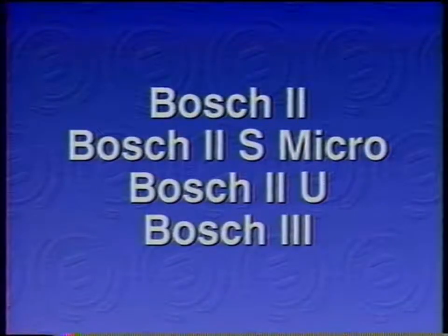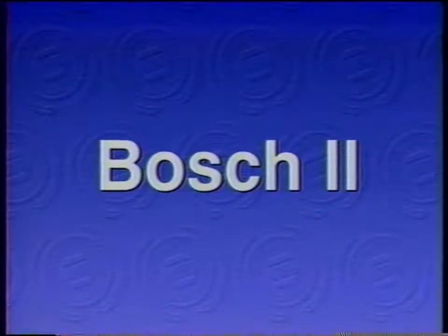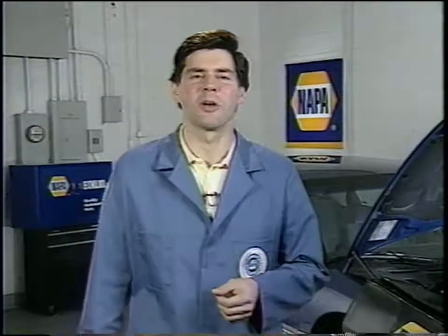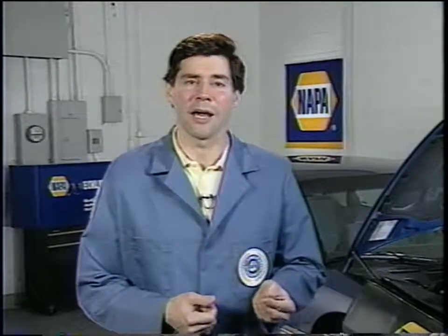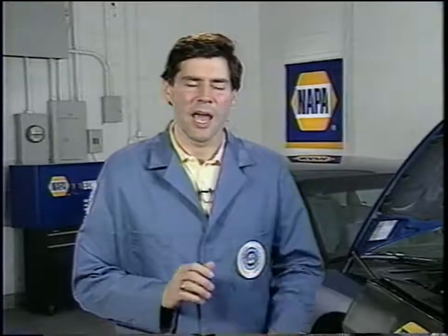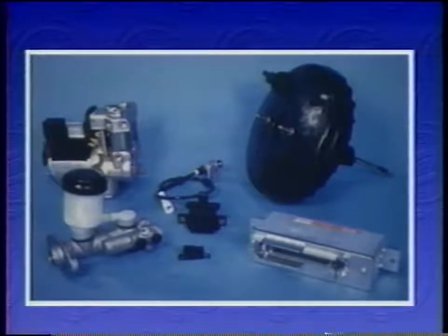Of the 4 Bosch ABS configurations, the Bosch 2 has the widest range of applications. And since it's been around the longest, beginning in 1981 on the Mercedes and on the Corvette in 1986, it's also the one you're most likely to work on. The Bosch 2 is in many ways the basis for the entire Bosch ABS lineup. If you understand its components, then it's easy to understand each of the other configurations by how it differs from the Bosch 2.